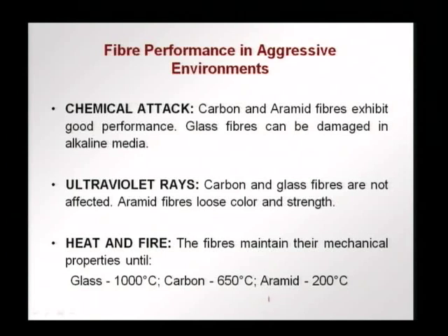This is also important because when we are strengthening a structure, this composite is generally on the exterior, on the outside surface of the concrete element or whichever element we are reinforcing. So, if there is a fire, there is a high probability that the temperature of the composite increases, and if this temperature is low or the fibers lose their mechanical properties very quickly, then the building will become unsafe before it is evacuated. So, the limitations under high temperatures should be known and analyzed when we use a fiber reinforced polymer in strengthening applications.